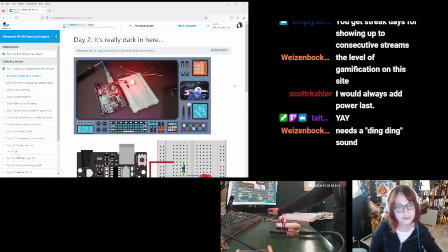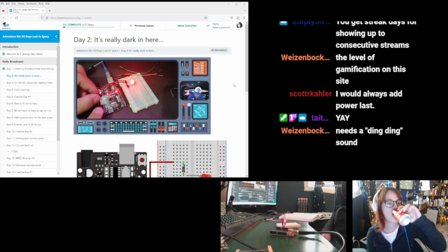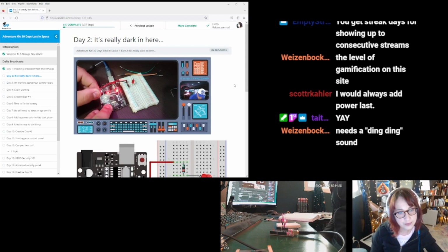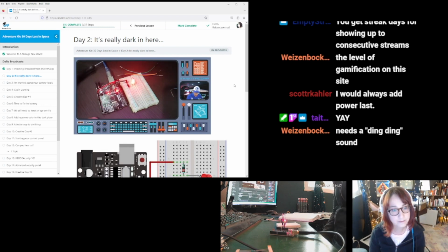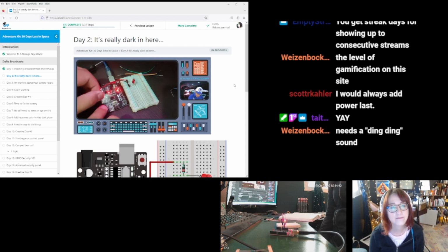We've now figured out how to turn the lights on. When I have a complete circuit from 5 volts to 0 volts, passing through the resistor and through the LED, I am producing light. So that's progress, but now what we'd like to do is get the Hero involved in an intelligent way. We'd like the Hero to take over the job of connecting and disconnecting the voltage to our circuit.